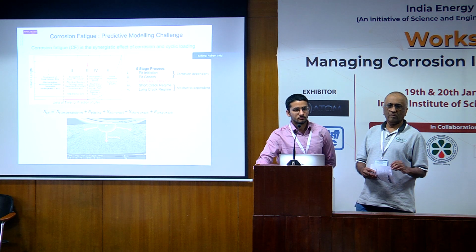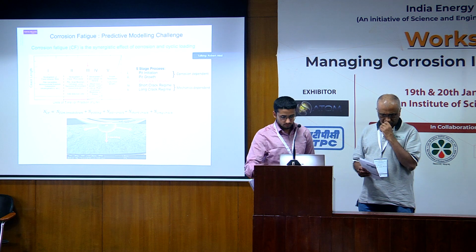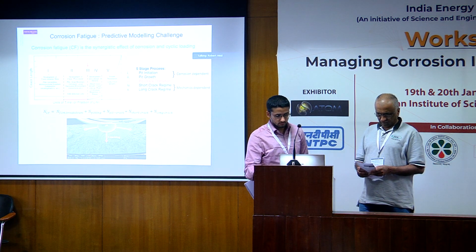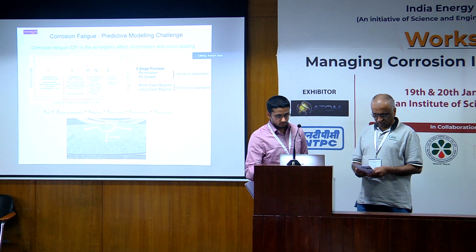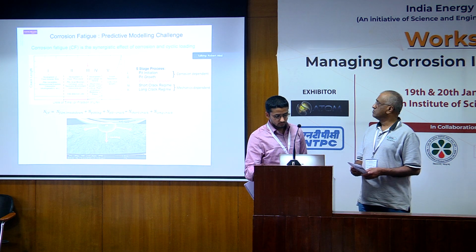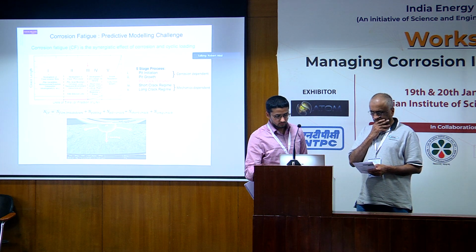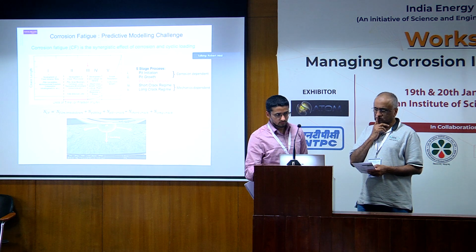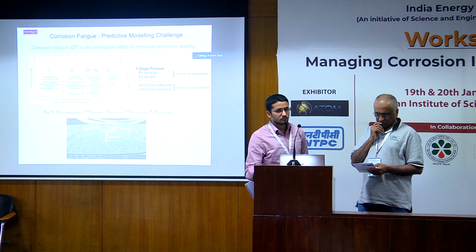Yeah, I think the work that we did highlighted that there is a possible risk of conservatism if you use a fracture toughness that's measured where you have the crack tip opening displacement well away from the actual crack tip. You might argue that if the fracture toughness was predicted using the standard method, then you wouldn't expect any failure in our materials.